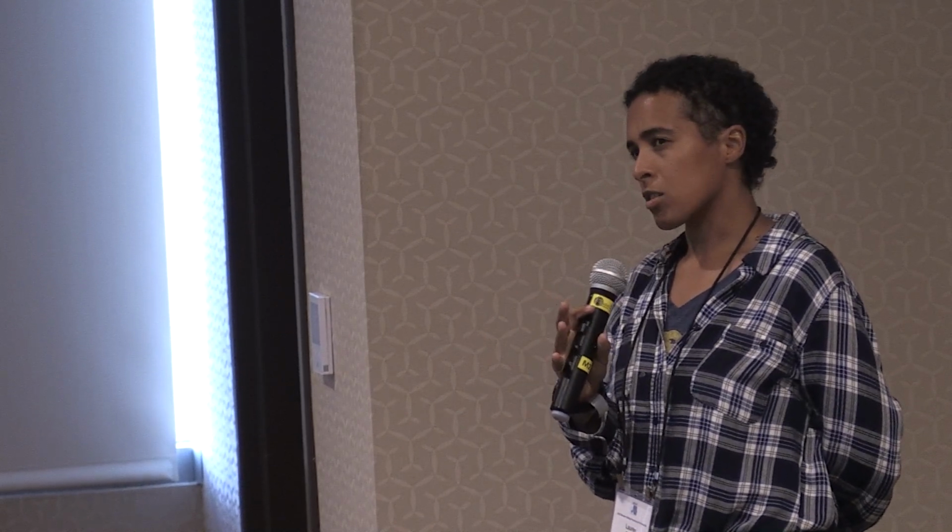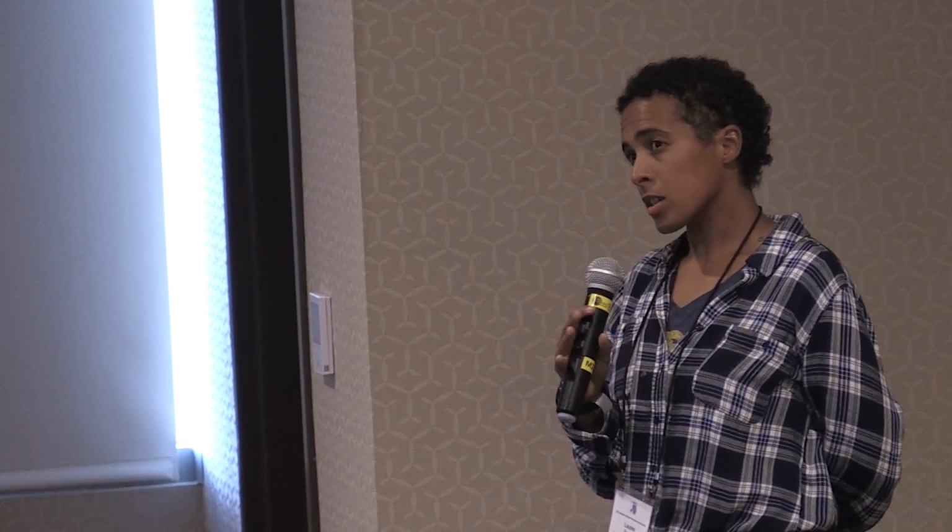So my question was, I'm not overly familiar with the carbonation thing you were talking about. So when you said that the purple or whatever shows that there's no carbonation, can you speak on whether that was a positive thing or negative or neutral? I'm just not familiar. So carbonation is a drop in pH of the concrete pore solution from the penetration of CO2 from the air into the concrete.